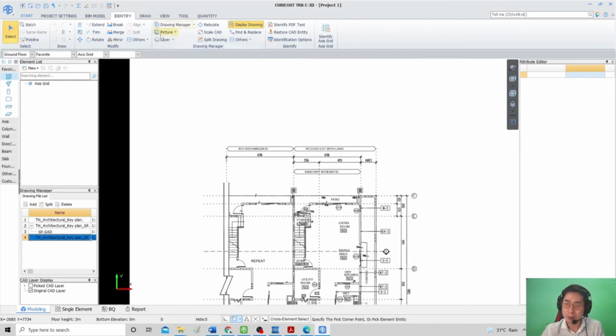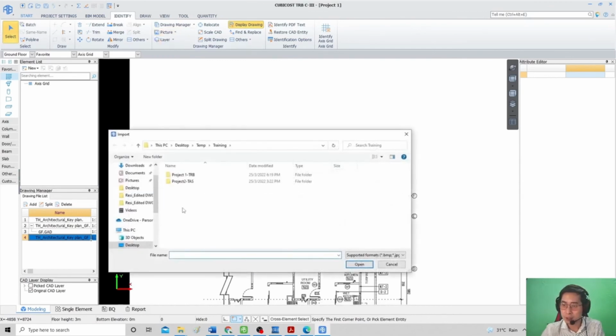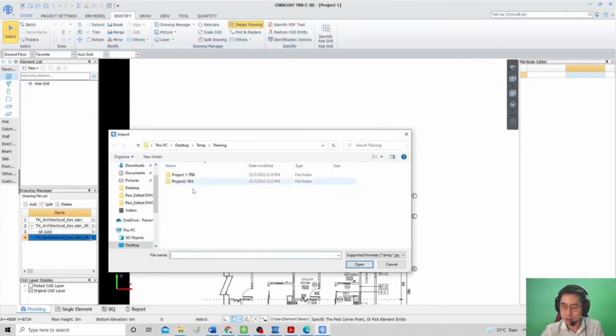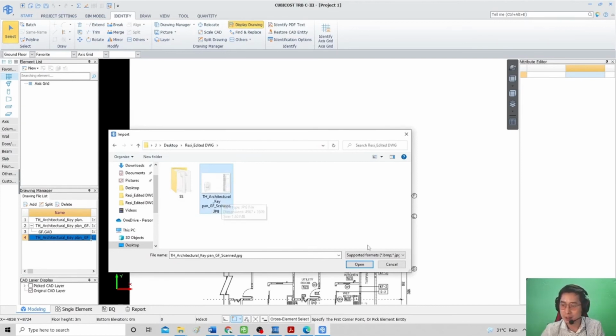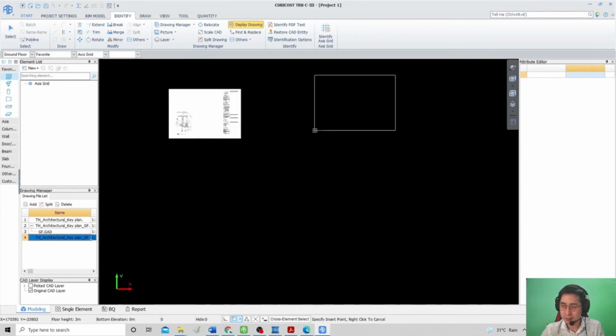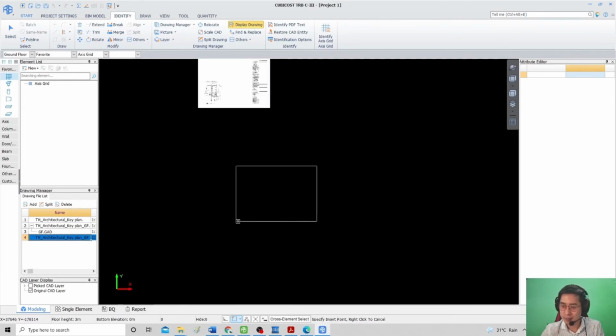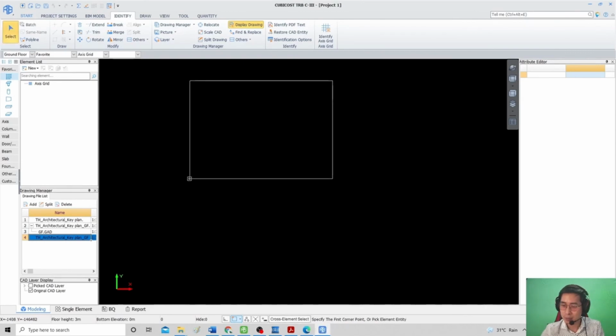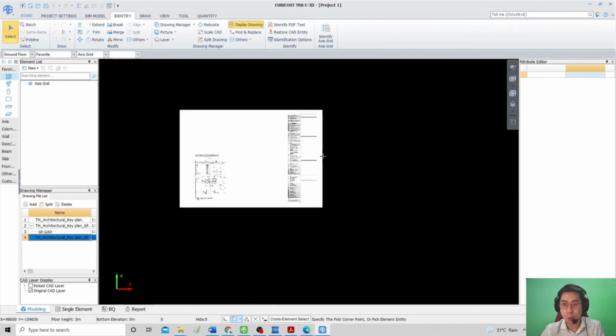The next step will be picture. Import picture. Open up my file, select the file name, location, Control C to copy and paste over here. Yeah, you see, this is a picture over here. Just now you could not see the picture, right? Okay, because by pressing this picture, you can import these two formats, BMP and JPG. Press OK. It will appear something like this, the square. Once you click on the area to import, the drawing will be imported over here.